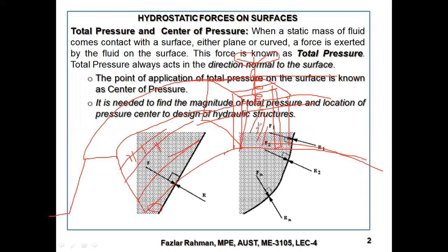And if you figure that out, then you can design that plate. What will be the thickness and what will be the material? Okay. And how can we support it, because pressure will work everywhere perpendicular to the surface of this plate, right? So you need to figure out how we can keep support, how much will be the force there.